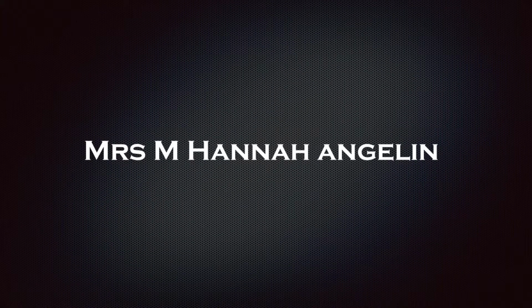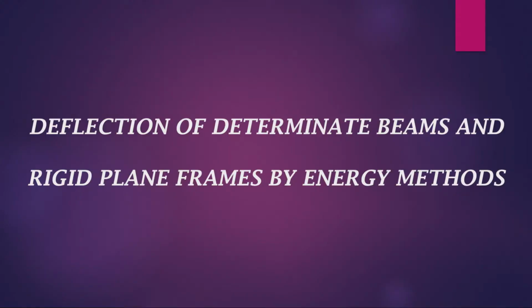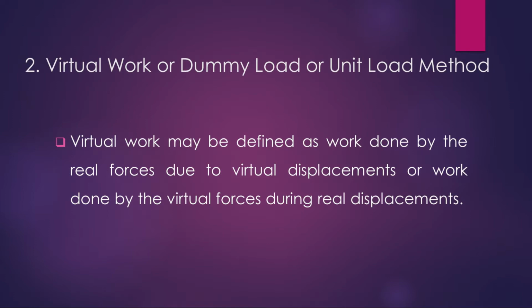In this video, we are going to discuss how deflection and rotation can be determined for beams and frames by the unit load method, or virtual work method, or dummy load method. Virtual work may be defined as work done by the real forces due to virtual displacements, or work done by the virtual forces during real displacements. Virtual means imaginary. We shall see the principle of virtual work.